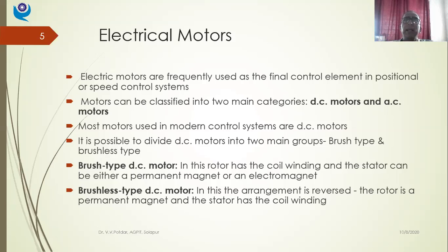So Francis turbine is a reaction type turbine, if you remember. So the runner is rotated by the reactive forces generated by the fluid pressure, isn't it? So that reacting ring has got vanes along the periphery, and I have got the runner, that is the rotor runner, which has got vanes or blades. So this ring at the periphery, which is also called a control ring, is rotated in such a way that I generate a reactive jet, so that I generate more pressure change, and in the process the runner moves.